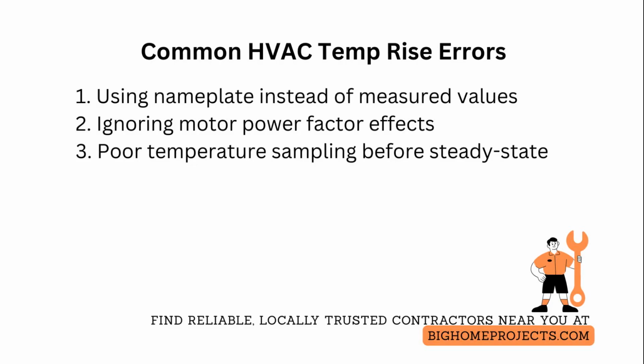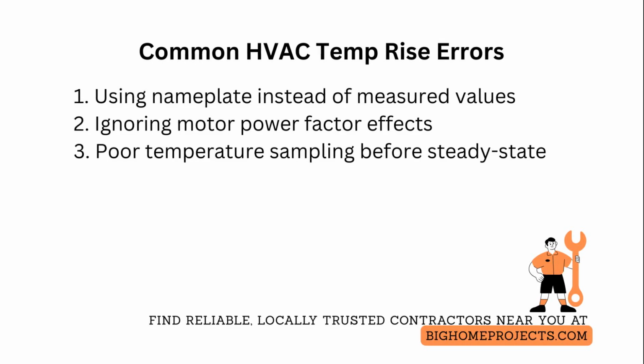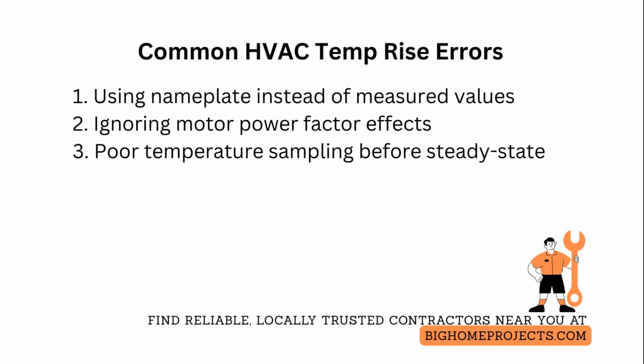One of the top issues is ignoring power factor on motor-driven heaters and assuming unity, which underestimates real power. Fix this by obtaining the motor power factor from manufacturer data or measuring it with a power quality meter, then include it in watt calculations.